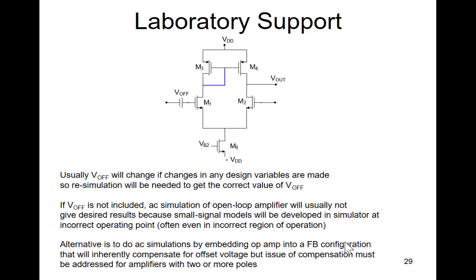Do they represent the signal you really see at the output of your circuit? No. All they do is represent what the output would be if the circuit were completely linear and you put that big input in. So keep in mind, any sort of AC analysis is inherently a linear analysis. They've already linearized the circuit before they do the gain calculations of the frequency response. Does that make sense?